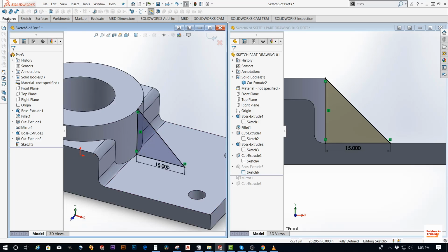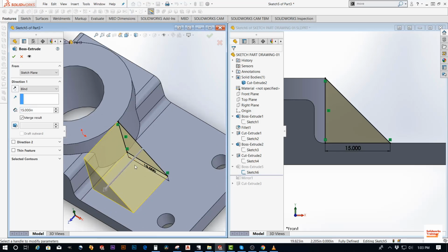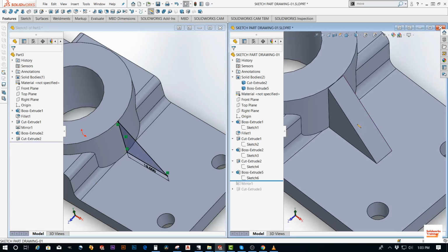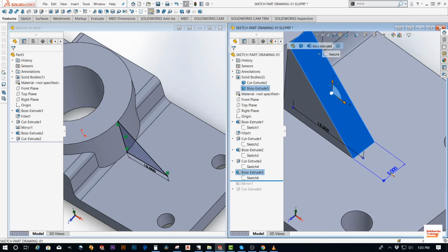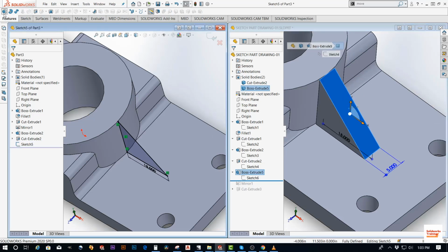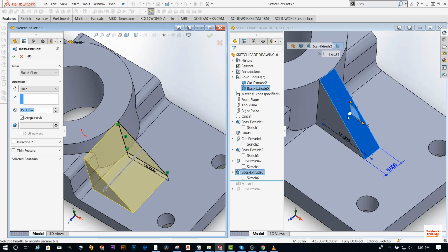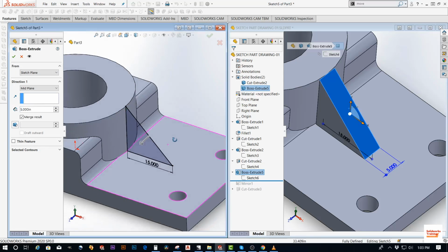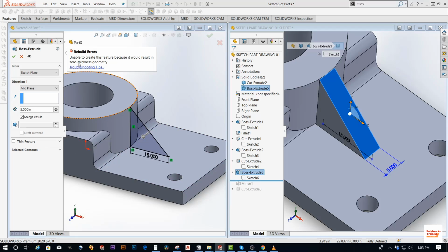So we can now extrude, but then we don't know the width of the extrusion. Let's take a look at our guide. So let's click this. It's a 5 inches extrusion. So we'll do it again, 5 inches. And we also notice that this one is extruded both ways, so we have to select the mid plane and then input the 5-inch width.